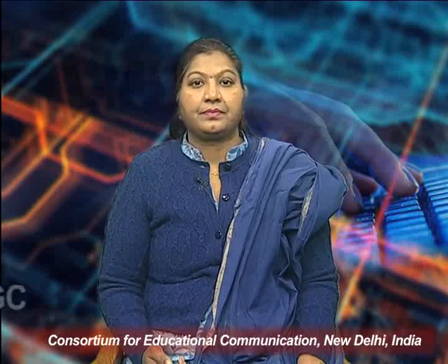Now, there are transducers that work on these principles, the passive transducers. If you take an example of a passive transducer, then we will take the potentiometer. A potentiometer varies the resistance with a change in the position or length that is converted into voltage and current using a power supply. So, the potentiometer is an example of the passive transducers.